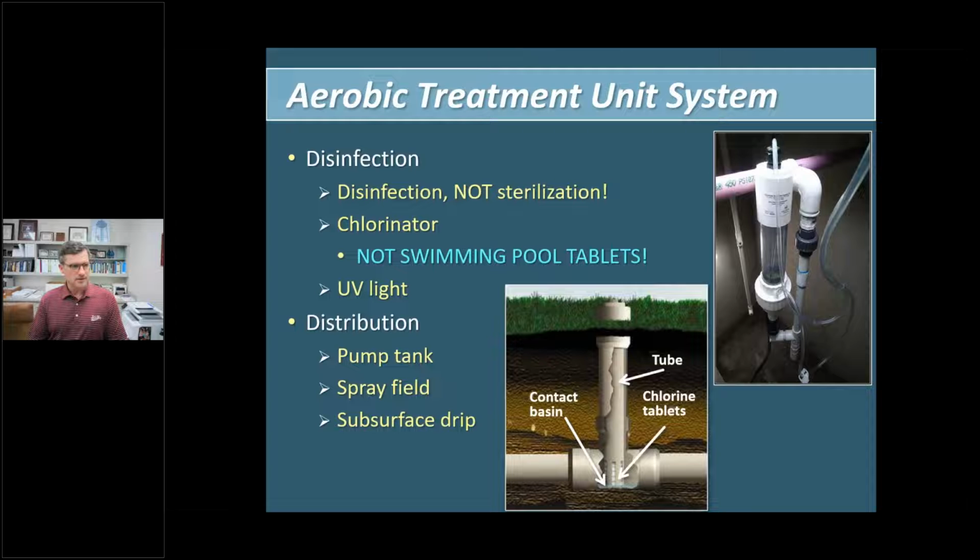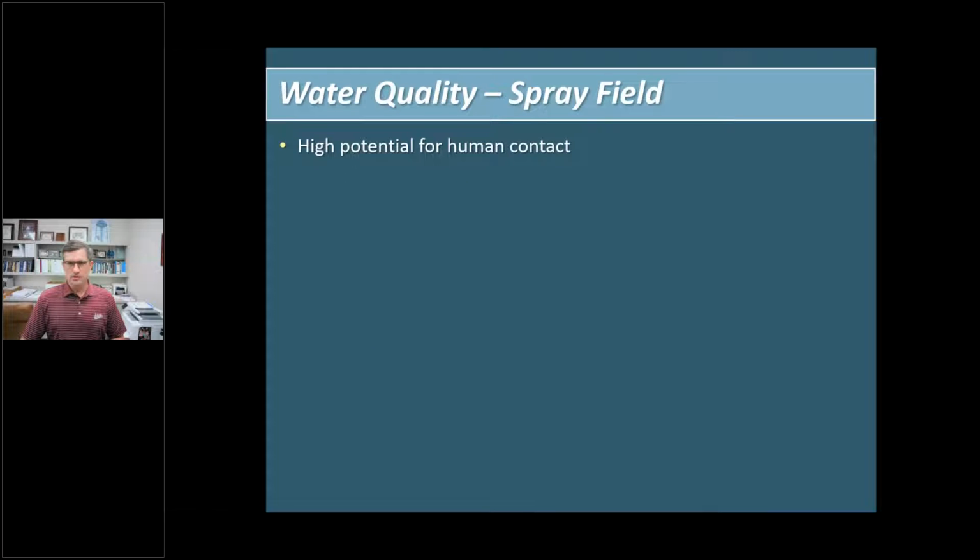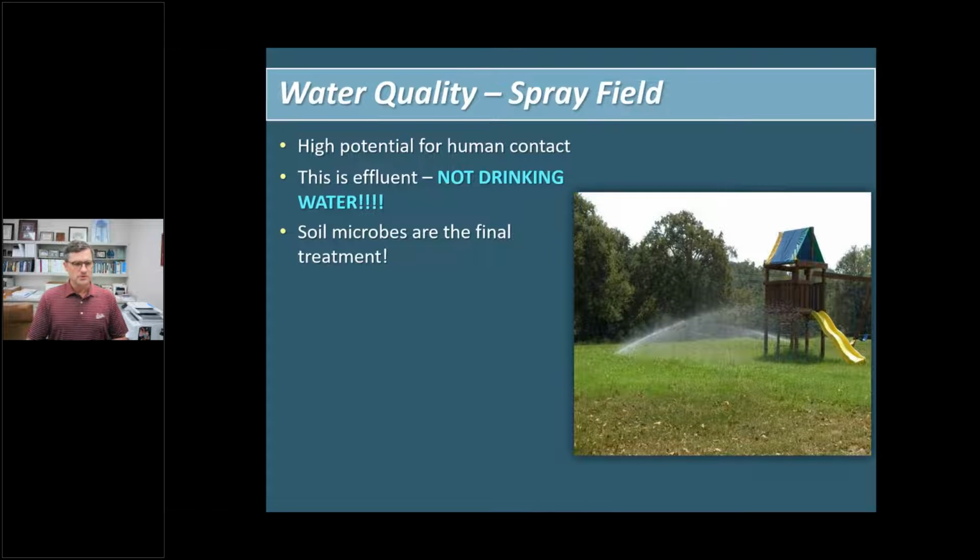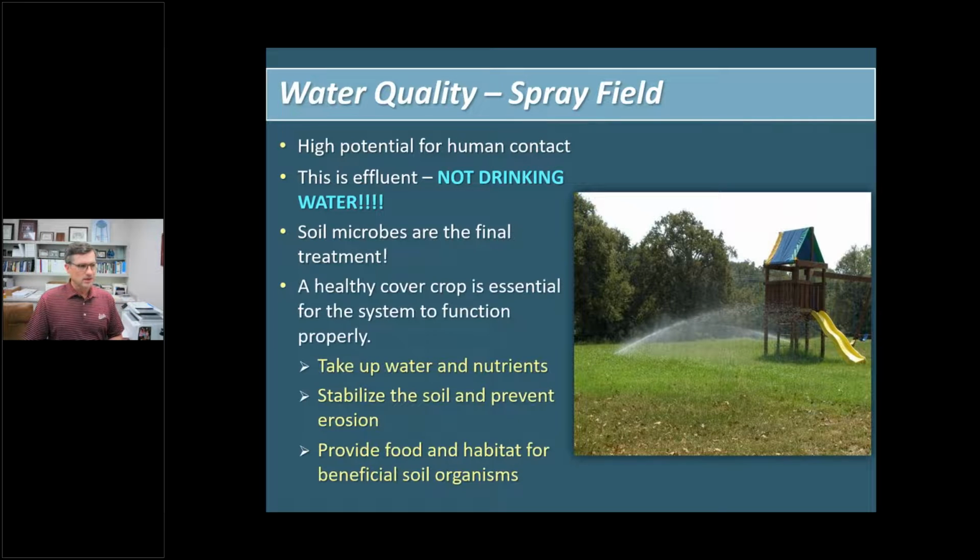disinfecting, killing the bacteria. All right, so dealing with the distribution, we look at the pump and tank, spray field, or a subsurface drip. All right, moving along. So dealing with our spray fields, high potential for human contact, yes, no doubt. This is effluent, so it's not drinking water. I jokingly tell people often that have that, do not drink that, no doubt. Soil microbes are the final treatment, so you're hopefully thinking that your soil and the grasses are going to absorb and utilize this. Healthy cover crop is essential.